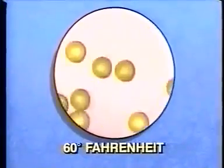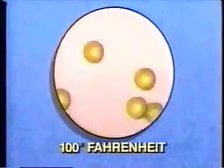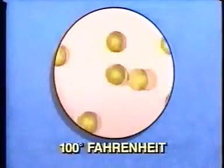Viscosity is caused by friction or drag resulting from the intermolecular forces of liquids. If the amount of friction is high, then more time will be needed for the liquid to move. The intermolecular force decreases when heat is added to a liquid. When this happens, viscosity decreases. The viscosity of a gas, on the other hand, is influenced by the friction produced by molecular collisions. The number of collisions increases at higher temperatures. So if the temperature increases, the viscosity of a gas increases.